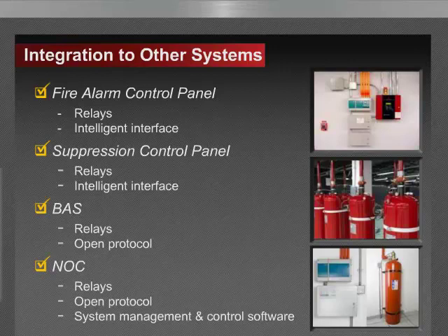The idea is just really important, to take a single pipe across multiple air handling units. You're then taking sampling ports and extending them from one air handling unit to the next. Now, if you've got air handling units cycling, where you have one that has more velocity and more pressure than the other, you could actually create a Venturi effect. So the challenge is that you could force smoke the opposite direction if you're taking holes from one pipe.